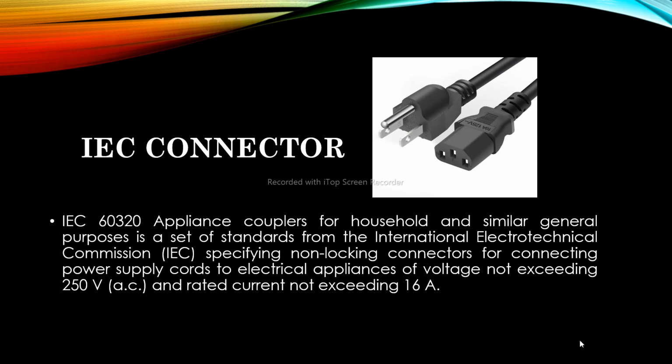IEC connector. IEC 60320, or 60320 appliance couplers for household and similar general purposes, is a set of standards from the International Electrotechnical Commission, or IEC, specifying non-locking connectors for connecting power supply cords to electrical appliances of voltage not exceeding 250 volts AC and rated current not exceeding 16A.